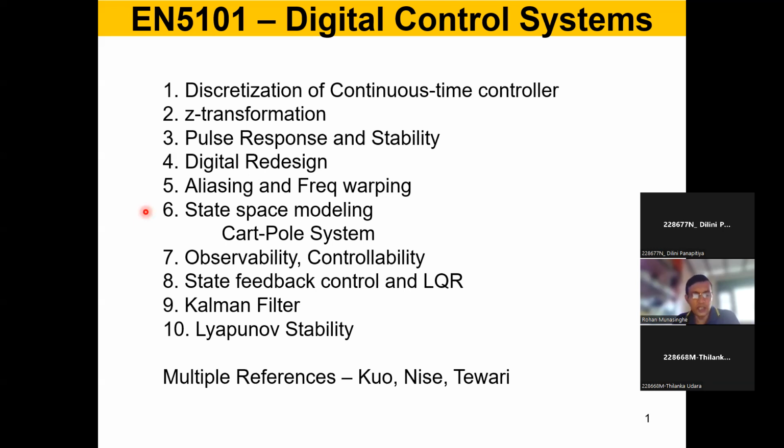And we got the differential equation that described the plant dynamics, how the plant changes. If you look at the RC circuit, we got a first order differential equation. And for the shock absorber, we got the second order differential equation, right? And for complicated systems, you might get third order, fourth order, fifth order, high order systems. And now this is going to be an increasingly difficult problem to handle, the differential equations of higher order.